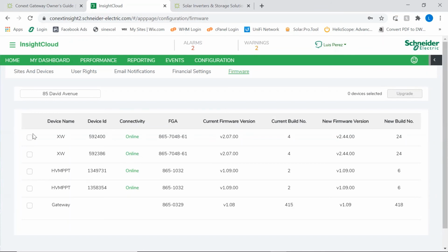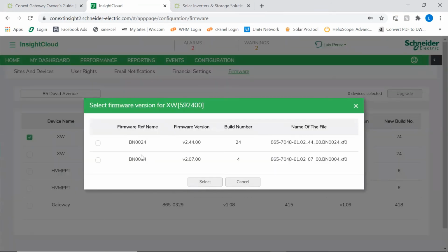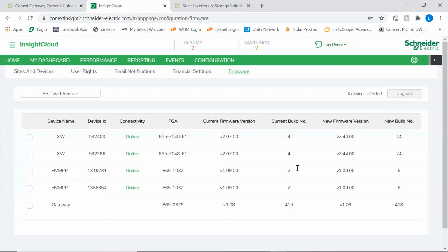So you will see here these are the devices. You can select and update the software on any of the devices remotely. To be clear, if you want to do anything which will set the system to standby, you need to keep in mind that that's probably going to power down the internet and lock you out of the system. So for doing any of these remote updates, it's fundamentally important that the gateway has a backup power supply, so that the power outlet is connected to the national grid if available, and so is the internet to which the gateway is connected.